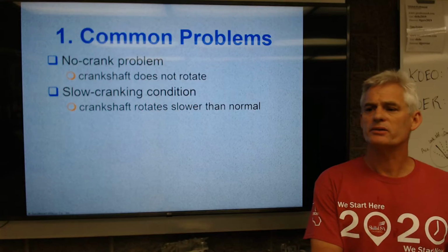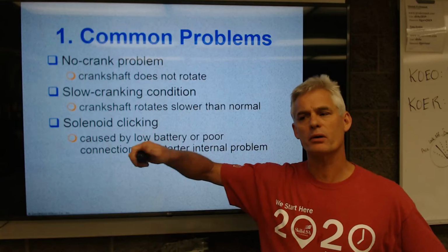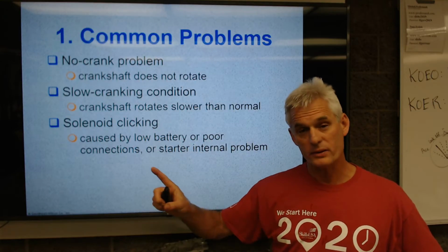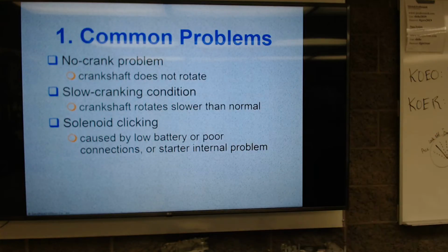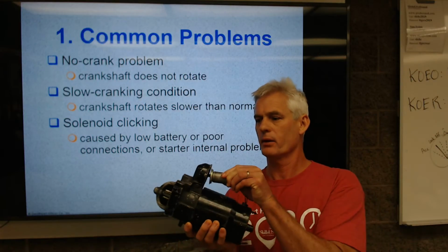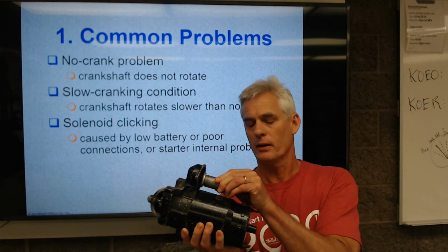Okay. Our third scenario is the solenoid clicking. In other words, I go to the crank position and I hear a loud click, maybe once. If you'll pause for a second, I have a starter here that I think I can make do this. It'll sound a little bit different in the engine than this one here, but the clicking will just be one click, or sometimes we'll hear a rapid clicking.